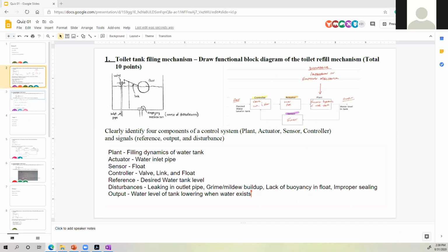I guess that's more the mechanics of the desired water level, like how the water level gets to a specific level. But the sensor is the only input that gives you that desired level. Without a sensor, there is no external input of water, right? There's no other way the water can come in. Well, the water would come in regardless, right? No, if the float is all the way to the top, the water is not going to get in, because the sensor, which is the float itself, has already sensed that the tank is full, so do not send any more water in through the valve.